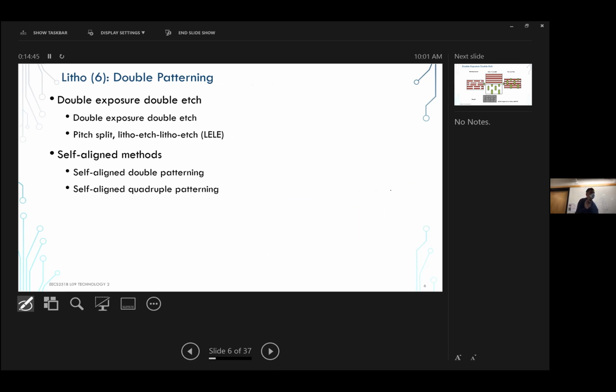In double patterning, before double patterning, features in one layer will all be printed in one pass by using one mask. They create one mask, shine the light on it, and make all polysilicon gates at the same time. And phase shifting enabled that to continue to finer resolutions.